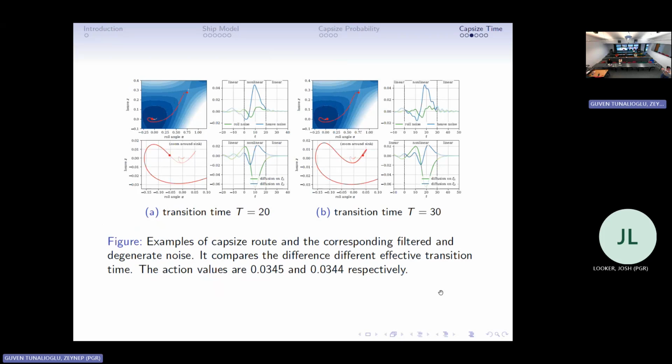So the x-axis is the roll. What the ship is doing in this case is that it spends a lot of time just repeating this kind of motion, up and down a little bit, and we see that the angle is getting larger and larger until at one point it goes from the pink to the red, which is too large. Then it pushes the ship away, following the red curve to the point near the saddle, and it capsizes.